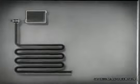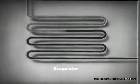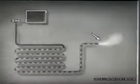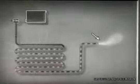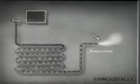Now the refrigerant goes on to the next main unit in the system, the evaporator. This is where the cooling takes place. The small particles of liquid refrigerant, with their pressure reduced, now begin to evaporate and turn into gas, absorbing heat from the air and food near the evaporator, just as alcohol absorbed heat from your arm. By the time the refrigerant reaches the end of the evaporator coils, it has absorbed enough heat to be completely vaporized. It is now a warm, low-pressure gas. This is the second stage of the refrigeration process, evaporation.